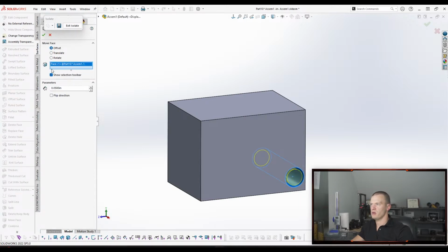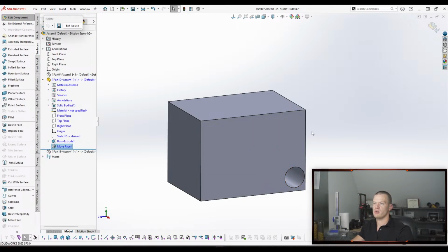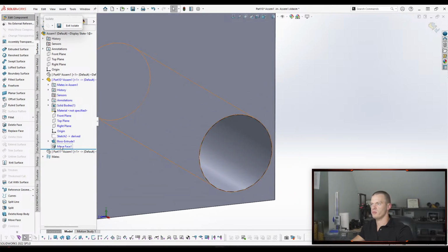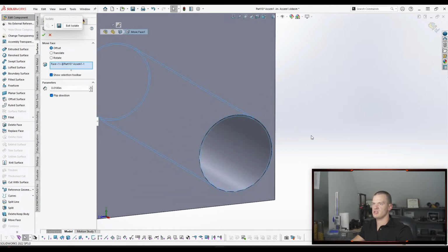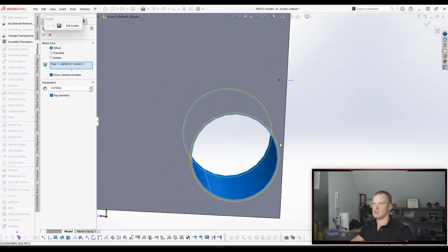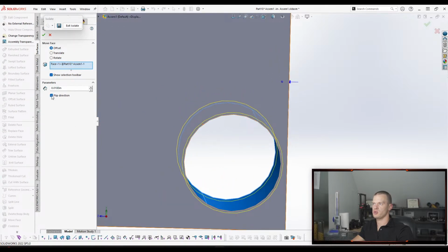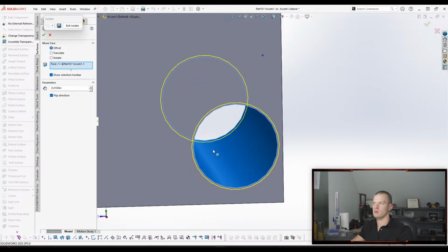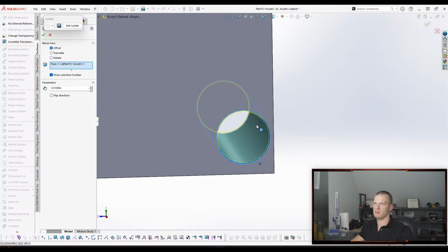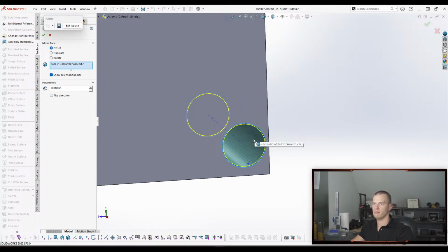So now we're here, right? 1/2 inch flip offset. I don't know if there's enough clearance here. Yeah, it's going to go through the wall, but call it 10 thousandths, right? Make sure your direction is correct when we're doing these really small movements, because with 10 thousandths, which way is it actually going, right? So double check your directions if you're moving in a small amount. But it's a great way to do press fits too, right? Like, say I wanted a 10 thousandths press fit or 20 thousandths press fit. Now you just flip your direction and you have what you need.